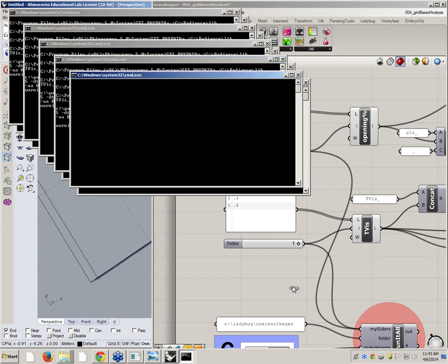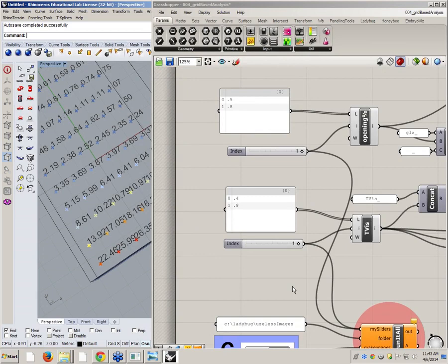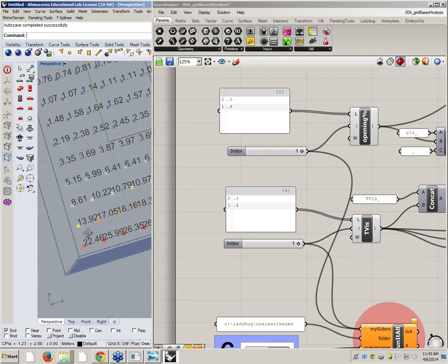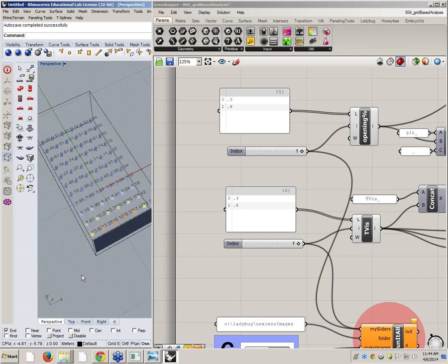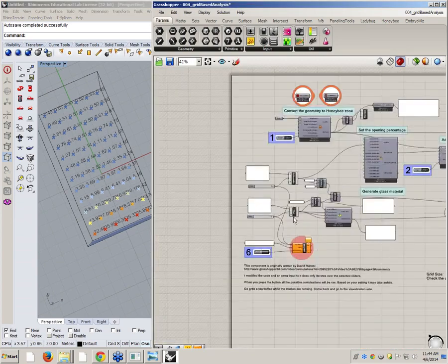And because this is an old version of Grasshopper, you have this bug in Grasshopper that a slider triggers 2 times. So it ran the analysis. I got the new result. You see now we changed this thing as something that can run the analysis with a single click. But this is not what you should have set up. You should set it up every time, I think, until you get really good at it. Now, this was a pain if you want to do it each time.